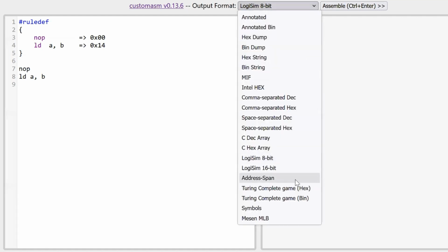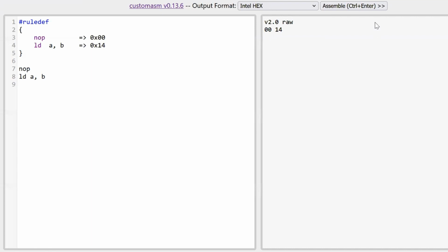And then it also supports Intel hex format. And looking down the road to when we actually have hardware implemented, we will need the Intel hex format to load our ROM code into our EPROMs. And ultimately, I'll write another hex loader that we're going to use so we can upload programs in real time to the computer.